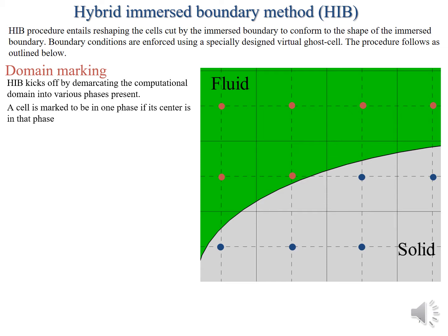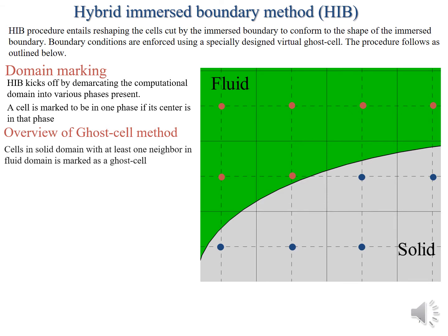But now the problem is a cell that is occupied by more than one boundary, because there are very many cell configurations that can happen from that. In fact, in 3D there are 108 different cell configurations, with all the cells that are in the solid domain, and programming that is difficult.